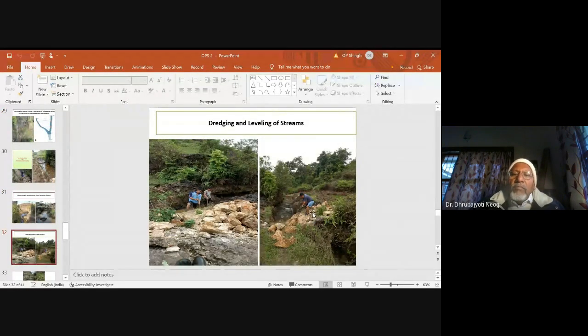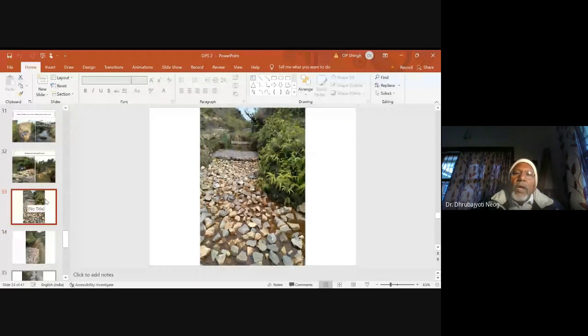See, in the beginning, the activities started like that: flattening of the channel and then putting limestone in it. And then you can see a finely constructed open limestone channel. Why is it called an open limestone channel? Because it is not covered with anything. It always remains in contact with the atmosphere. So it works in oxic condition, and that's why it is called an open limestone channel.